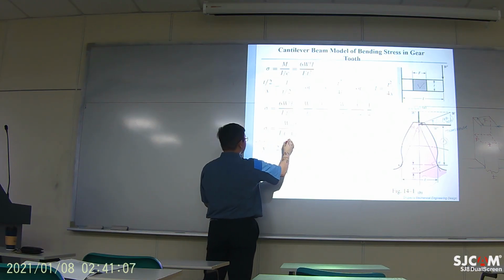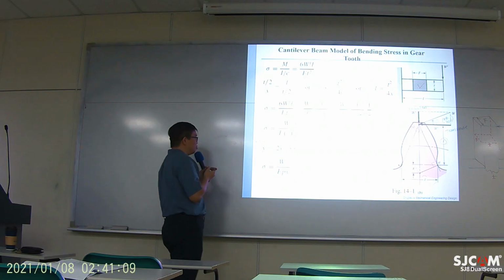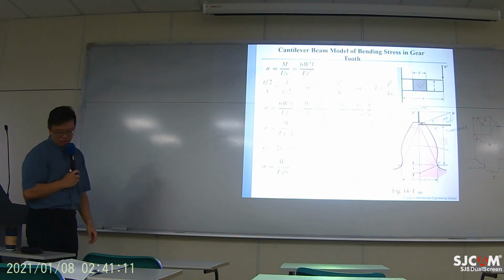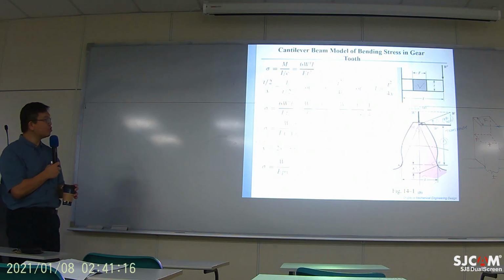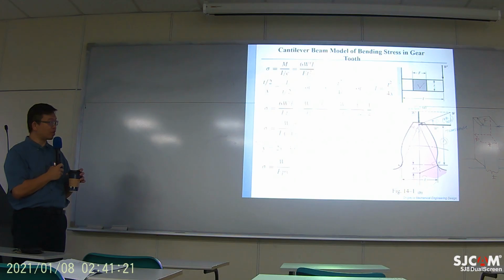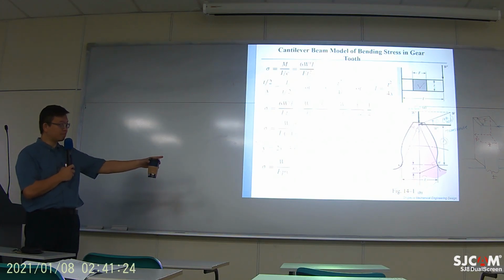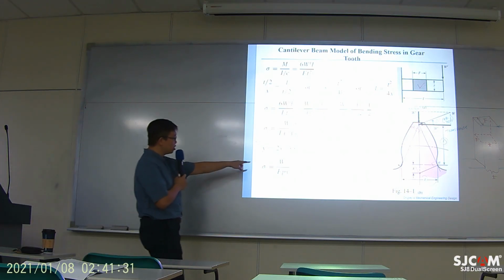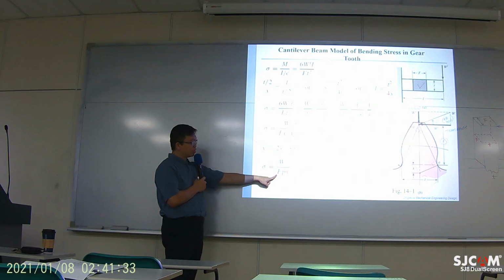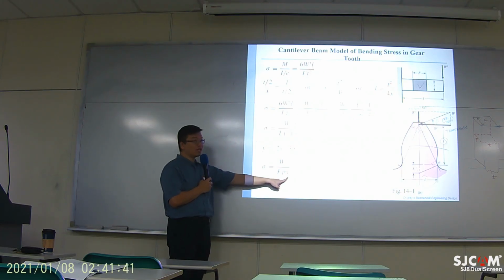Okay, so this Y is called the Lewis factor. So basically, you can apply this particular factor, and later on your stress analysis becomes the equation at the bottom, and that gives you a way to just pay attention to the transverse force, the face width, and P is the circular pitch, Y is the Lewis factor.